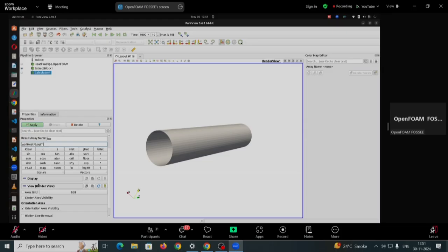Right? For a flow through pipe, you don't have one bulk temperature. Say if you had a flow over an external body, the free stream temperature is what you can use as a reference temperature. But flow through a pipe is a very different case. Even though I've demonstrated for this, here there is no one reference bulk temperature; the bulk temperature itself changes from inlet to outlet. If you read the theory, right? So this may not be an accurate representation, but my idea over here is just to demonstrate that something like this can be done.